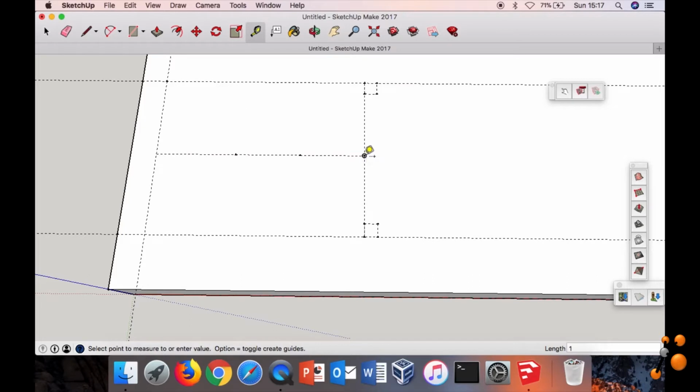What is important here is to now add this back focal length, which is 11.6. So it means that my LED will be until here, 5 millimeter distance. Then we have the edge thickness of 2. Let's put some font. So the edge thickness of the LED, then we have the curve of the LED until here. Here is the base of the LED, a flat part, more or less locked by here. And then from here to here, 11.6.